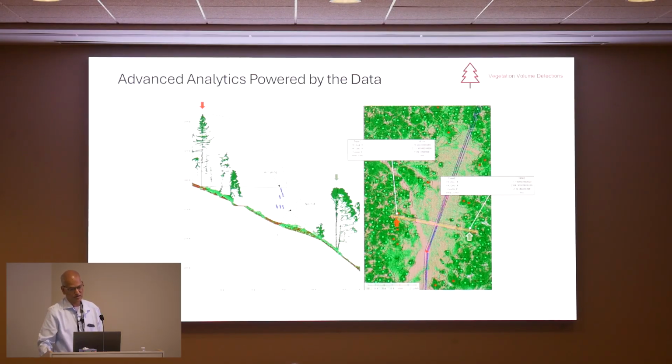In this case, the one on the left-hand side is a tree. Because you have very high density LiDAR, you also have exact information about the ground, including the slope and aspect, everything. With the tree height and the slope in consideration, you know when it is going to fall, whether it is going to hit. Or if you go to the tree on the lower side of the slope, you can also calculate if it is going to fall in this direction, whether it is going to hit or not. Those types of very detailed analytics can be done with the tree height, the ground condition, and the elevation information.